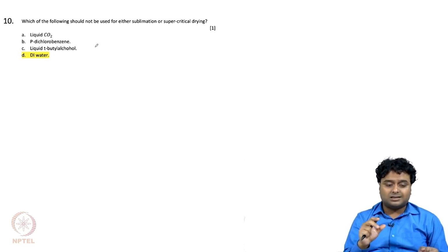You need to understand this point, that DI water is required for our usual fabrication process. So while we are doing fabrication, let us say etching or lithography, lift off, in those steps DI water is used. So ultimately after completing those steps, our samples are inside that DI water, because we have used the DI water to clean the sample.